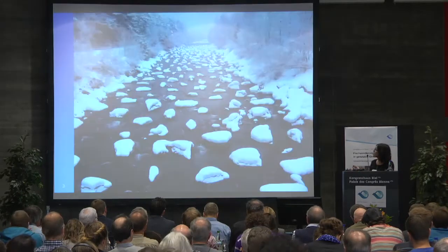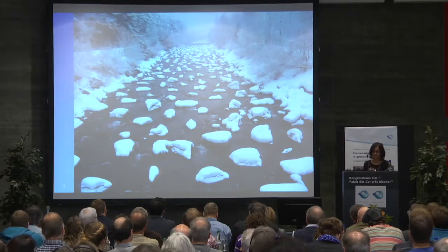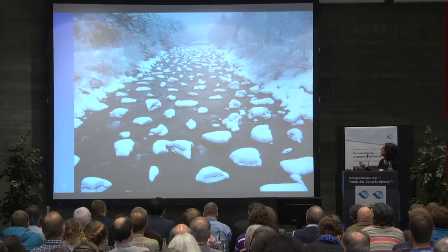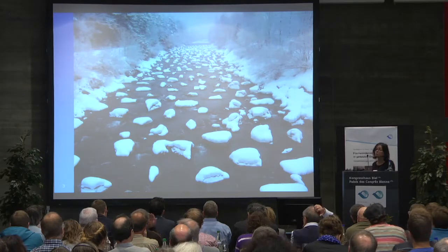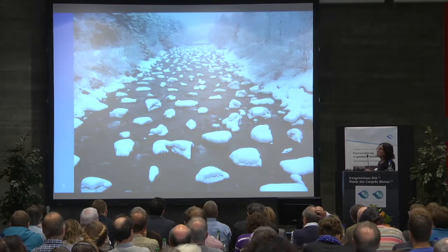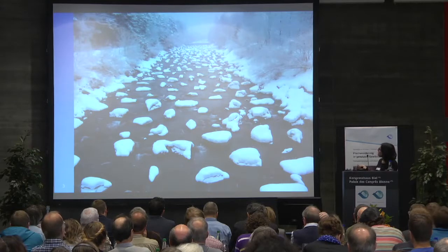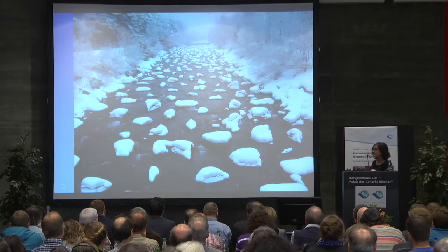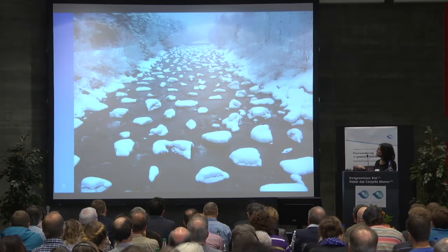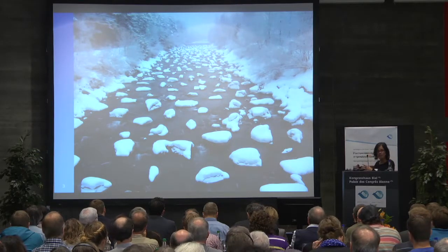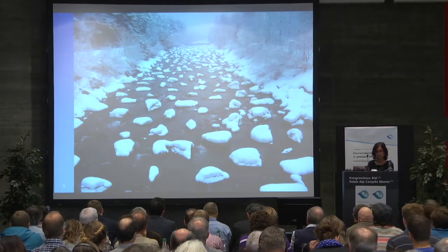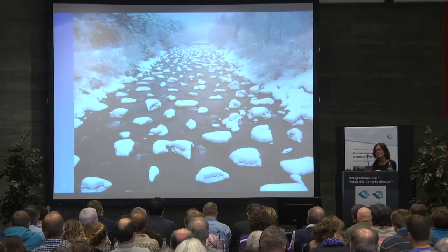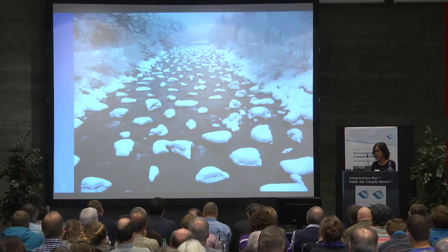Today, I'm going to talk about unstructured rock ramps, and I would like to define them on the basis of this beautiful winter picture. This is in the canton of Graubünden against the flow. And you see the rock ramp, which is characterized by randomly distributed rocks. There is no contact between the rocks. They are individual rocks. And there is no geometric structure.